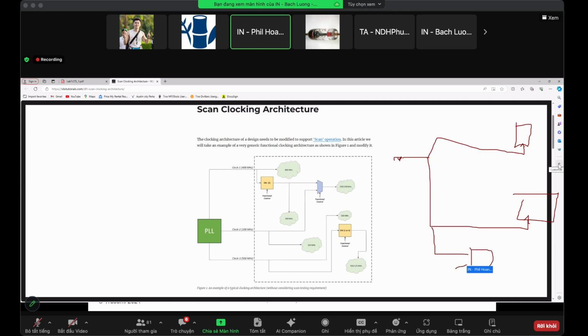By virtue, these are defined as clocks. Then the tool traces and says, this is a clock net, and this is a clock net. Since this is not a clock pin, over here is not a clock net. Anything between the clock definition point and the sync pins, you build clock trees automatically, so the buffers will be inserted.